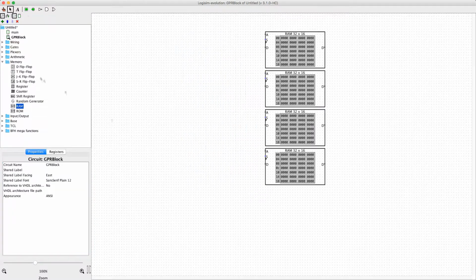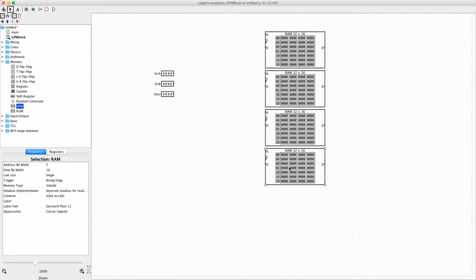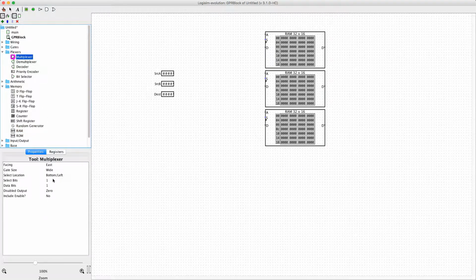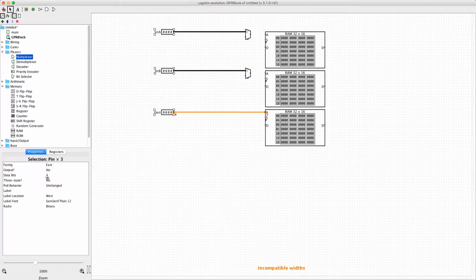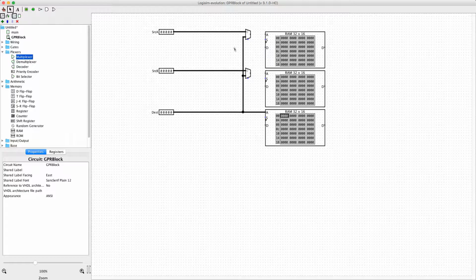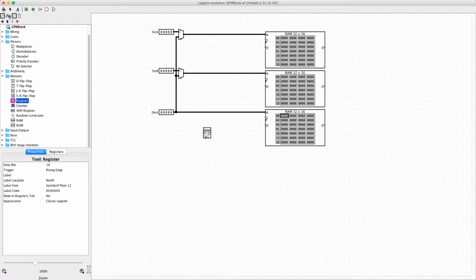The only difference here is that I'm using 4 RAM components to simulate the GPR component, while the actual GPR component is going to look like a single RAM component. It's also the case that this method of implementation isn't a good idea because all 3 RAM components must be synchronized when data is written to them. That's going to be quite difficult to accomplish. And it's not really something, I don't think, that can be accomplished very easily, if at all.